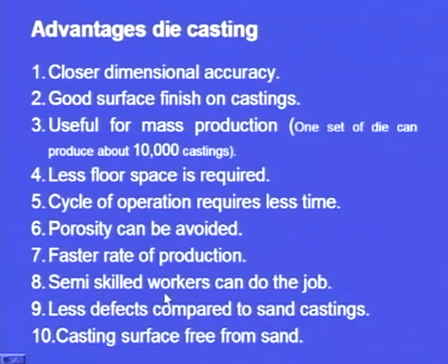And another advantage is even semi skilled workers can do the job. In the case of the sand moulding, especially for making the mould and for preparing the green sand, it requires high skill. If the moisture is more, that results in problem. If the clay is not controlled properly, that creates problem.